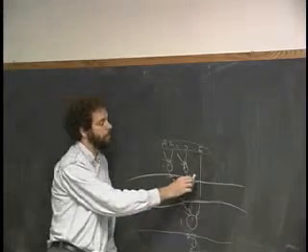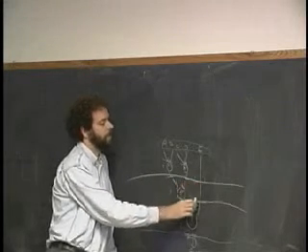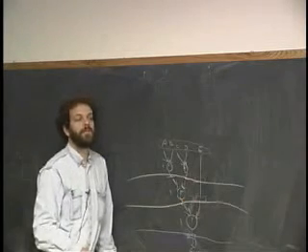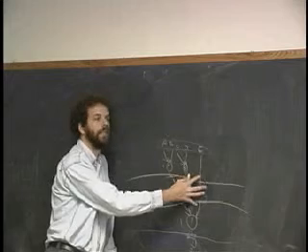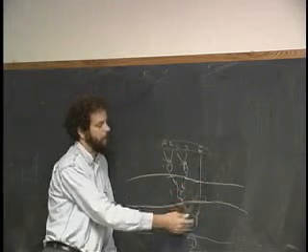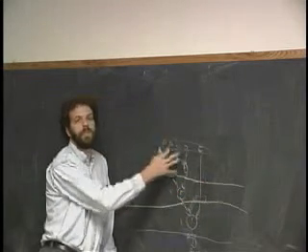It means putting registers in places where they seem to be doing no job at all other than to delay the signal and to hold on to the several values of E as we get ready to synchronize them and add them up to the values of A through D on the way down.